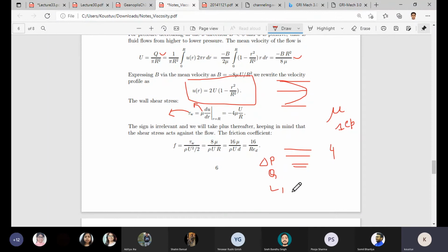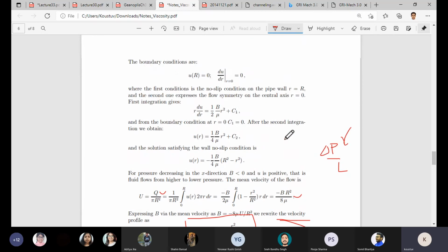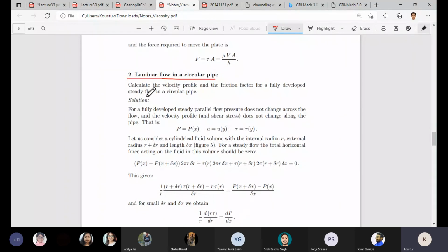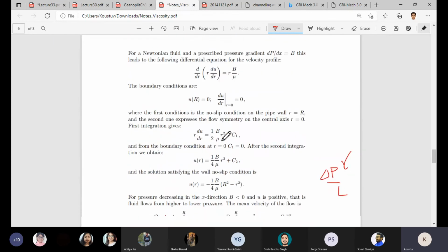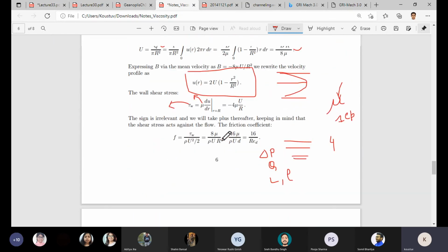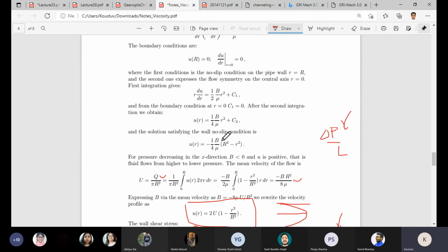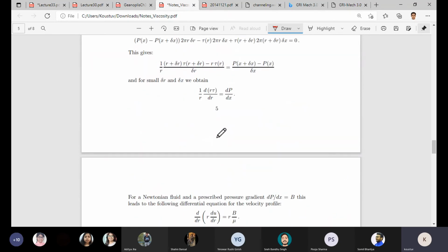And we know L, rho, these things we know. So through some quantities measured, we are calculating tau W and what is called DUDR. After that, we are equating them, or rather plotting them, and then calculating the slope of the curve to get the mu. So it is basically validating laminar flow in a circular pipe. Please remember that it is validating that, and ultimately we are calculating mu, which is basically constant because it's a Newtonian fluid.